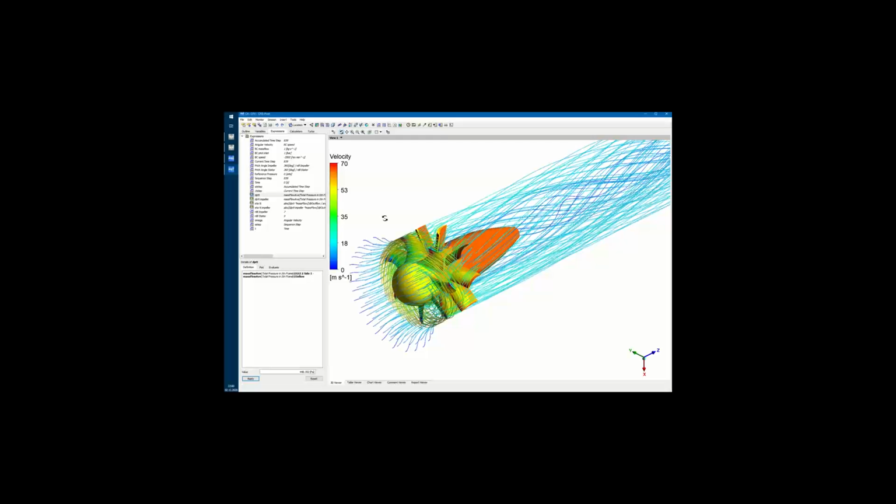The sizing and the blading and all this. What we don't recommend is loss model based performance map estimation. I don't know what the question means, but empirical data, yes, for creating the geometry. However, for getting performance data, we should run 3D CFD. Yep, and that's why the parametric relationship comes in very handy, so that we can explore the design space.